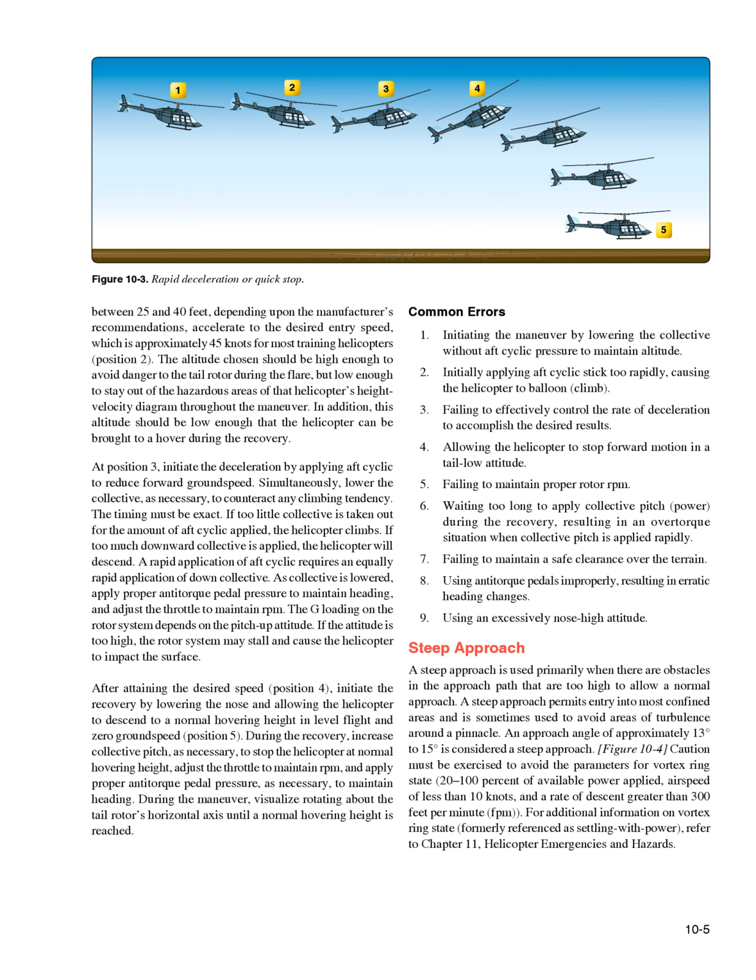As collective is lowered, apply proper anti-torque pedal pressure to maintain heading, and adjust the throttle to maintain RPM. The G loading on the rotor system depends on the pitch-up attitude. If the attitude is too high, the rotor system may stall and cause the helicopter to impact the surface.